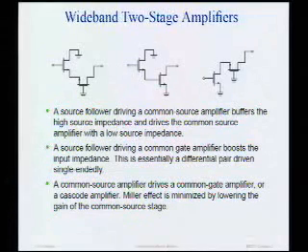All right. Another way to build a useful two-stage amplifier is basically, one of the big problems with our common source amplifier was the Miller effect, right? And we mentioned that if you have a low source impedance, Miller effect's maybe not too bad. Well, one way to generate a low source impedance is just to buffer the actual source impedance.